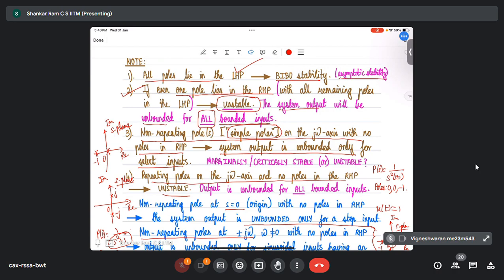So if I'm a steering engineer and I want to look at the vehicle cornering response, I better design my system such that I never hit a condition where my poles migrate to the right half of the complex plane due to operation. Then I retain cornering stability, but it's easier said than done, because our vehicles operate under a wide range of operating conditions. We have dry roads, wet roads, oily roads, slick, muddy roads, icy roads, and so on. So things change, and we have to live with it.